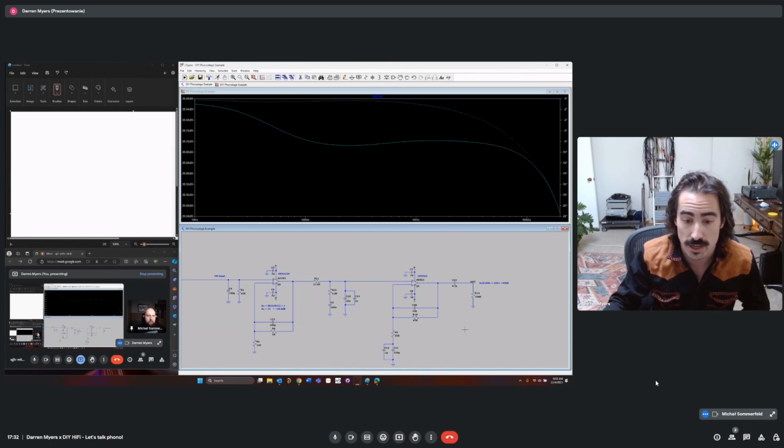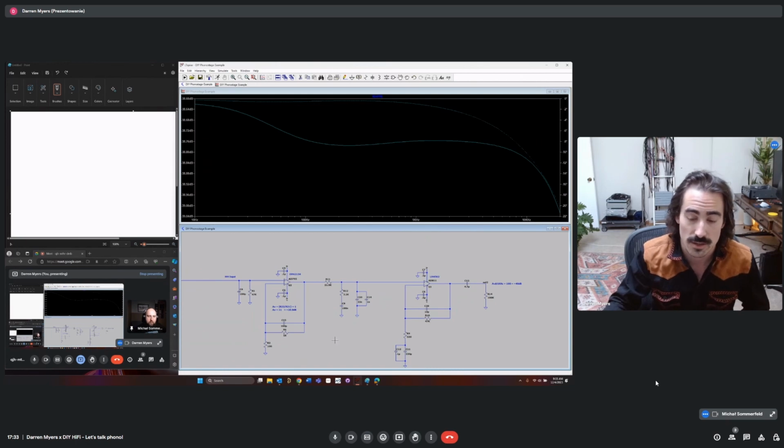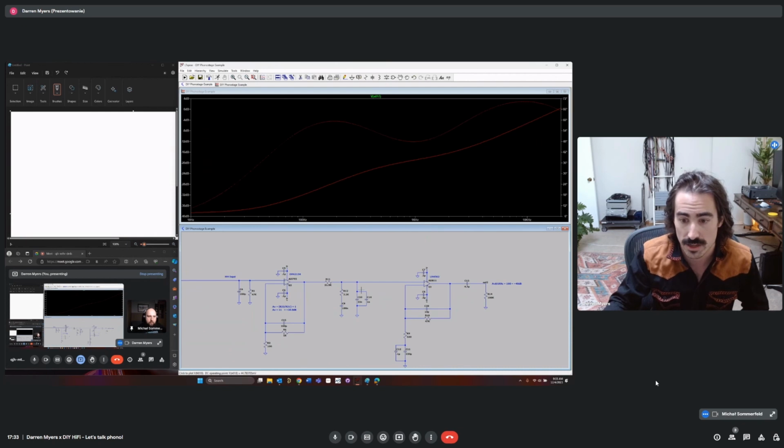And so why are we doing that? Why do we have so much gain? And the reason is that with the passive network, we actually lose 20 dB of gain right here. If you think about it passively, what are you doing here? We are bringing everything down to this lowest value. So the two curves to look at are, this is the phase, that's the phase, this is the amplitude, and that is the amplitude here.